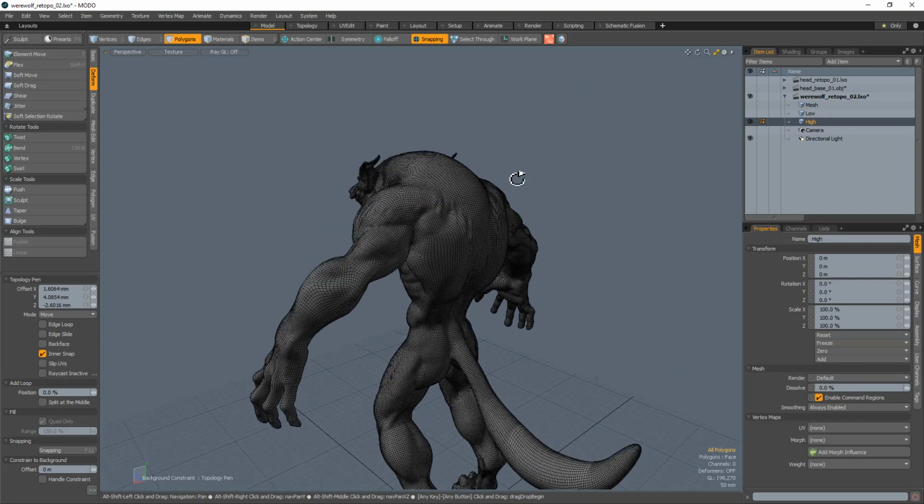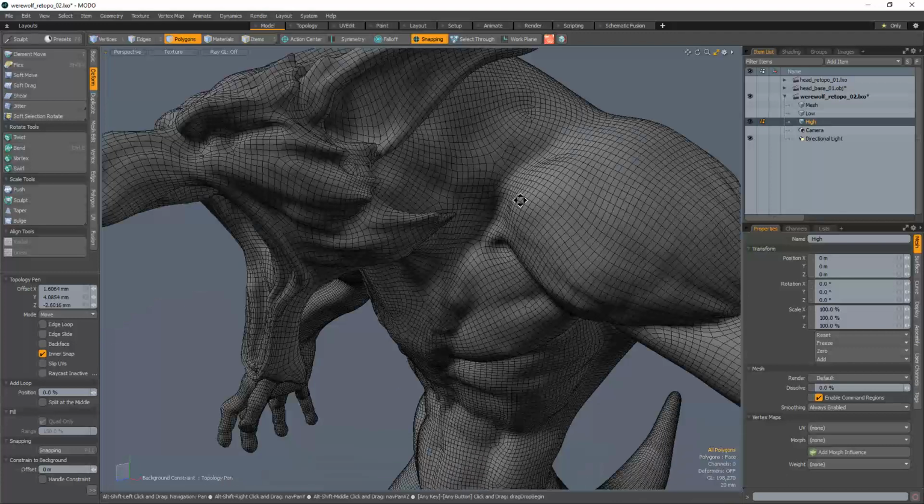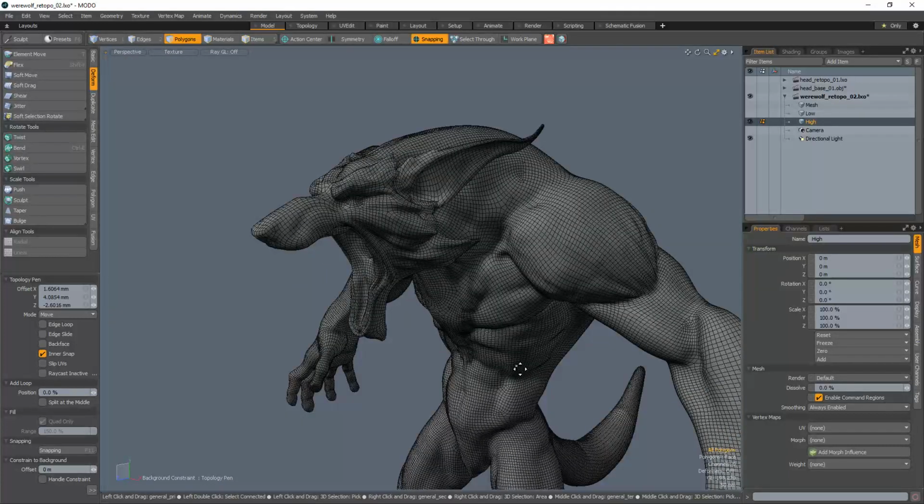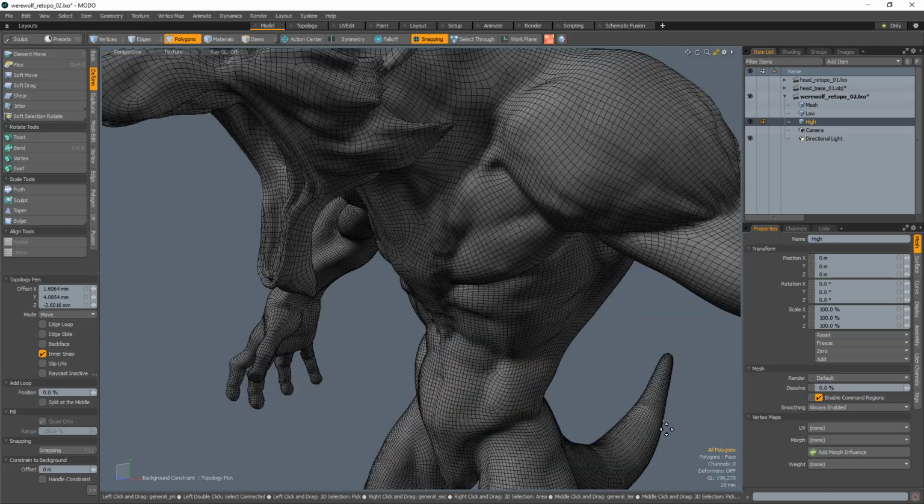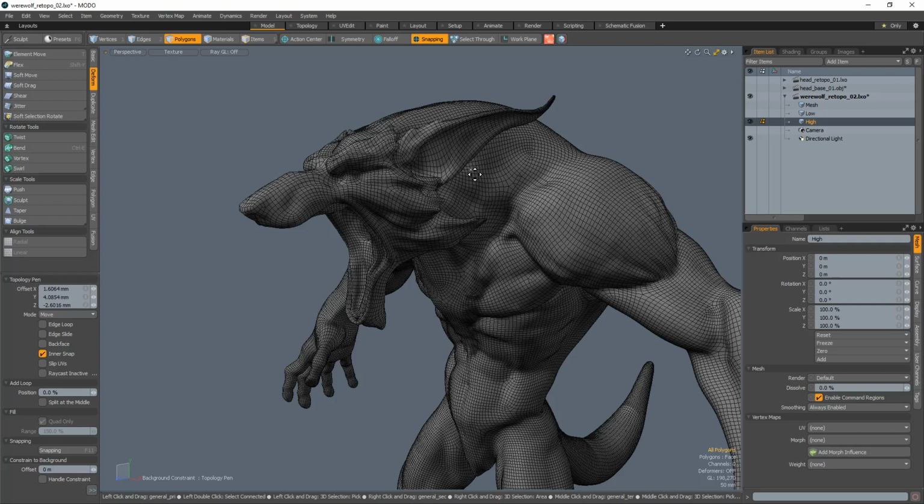You could have the earrings and the satchel represented using two different shaders, and with that in mind you would probably have them on two separate sets of UVs. Or, to increase efficiency and lower the number of draw calls, you could have the satchel and the earrings use the same shader, especially if those two things didn't necessarily need two separate shaders.